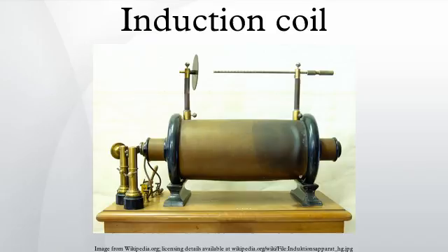The interrupter. To operate the coil continuously, the DC supply current must be broken repeatedly to create the magnetic field changes needed for induction. Induction coils use a magnetically activated vibrating arm called an interrupter or break to rapidly connect and break the current flowing into the primary coil.